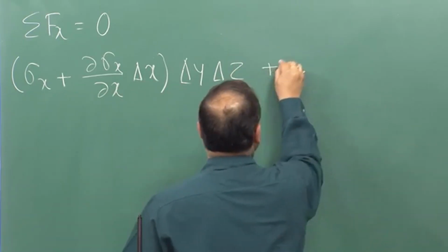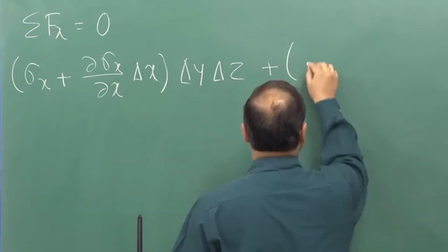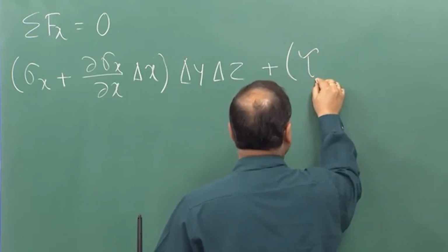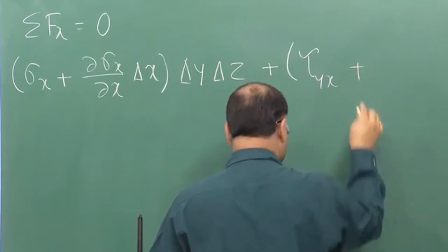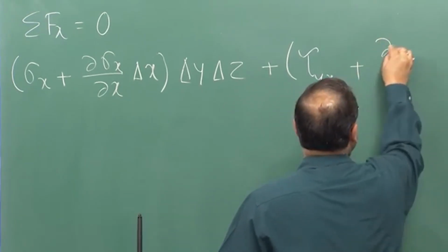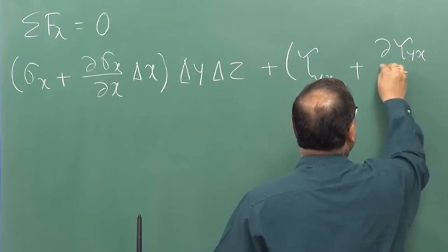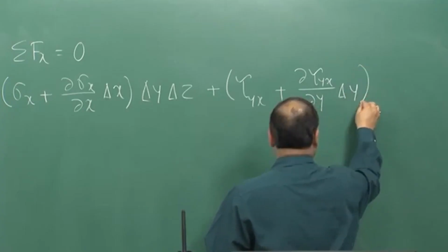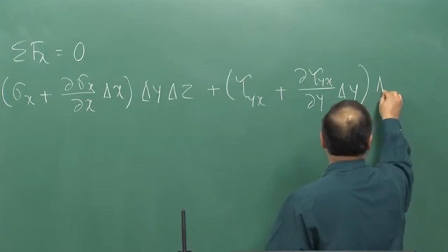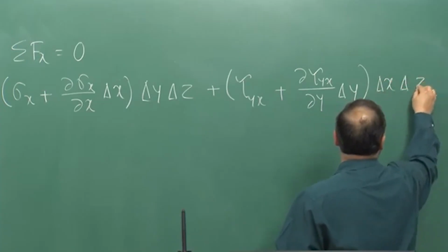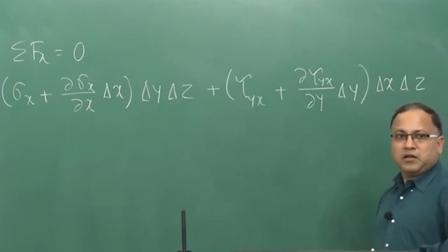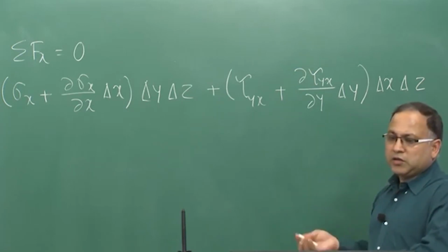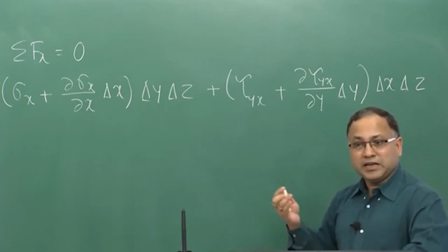Similarly, this is the stress tau yx plus del tau yx del y delta y, times delta x delta z. This is the force acting on the positive y plane along x direction.